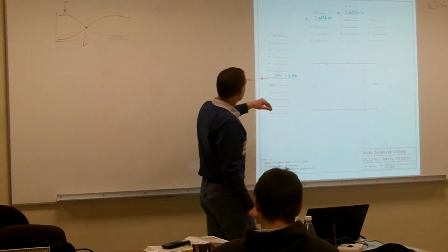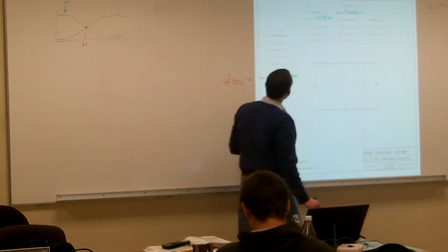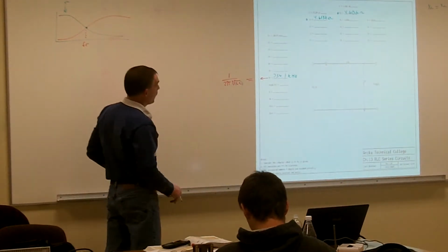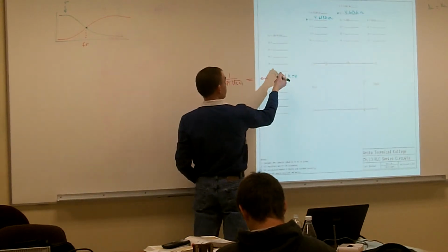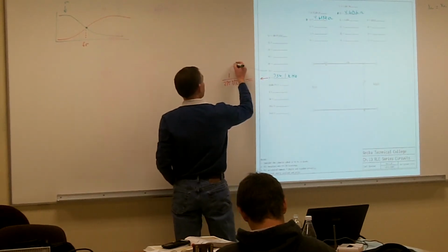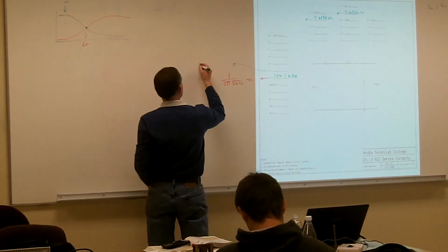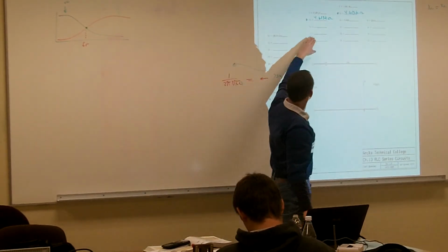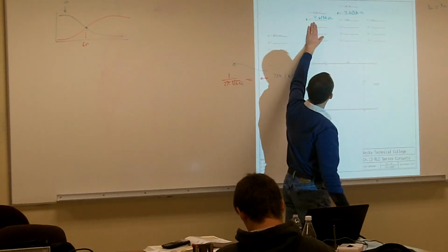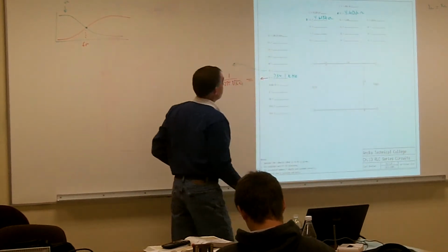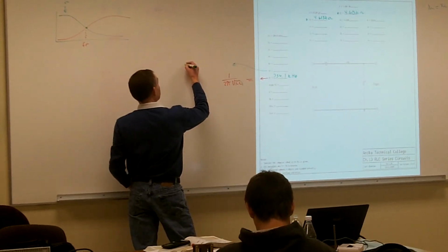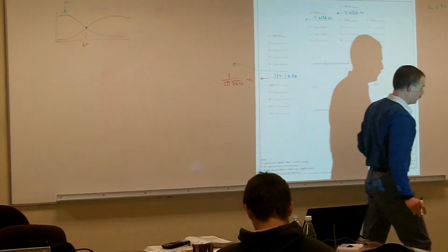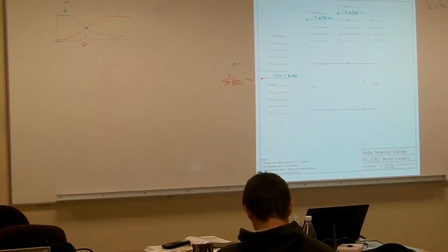All right. So now we got our X of C and we got our X of L. Now we can go ahead and calculate out what our X of T is. Our X of T is just equal to, if I add X of L plus X of C, so when I say that, we have to look at our vectors. Remember that X of L is going to be at our plus Y, X of C is at our negative Y, and our R is going to be at plus X.